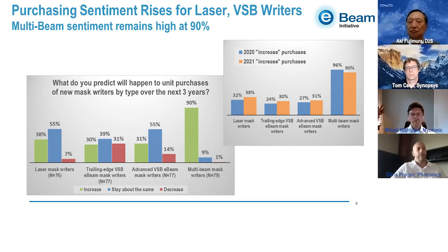This was a big movement for a while. Even AMAT came out with an inspection tool called the ERA, which really did not catch on much in the mask industry. It lost out to very high resolution: inspect every pixel, repair every dot. But if, at the same time we increase mask complexity, the industry could revisit a repair-only-what-prints model, that means a very different way of approaching the back end in mask making.